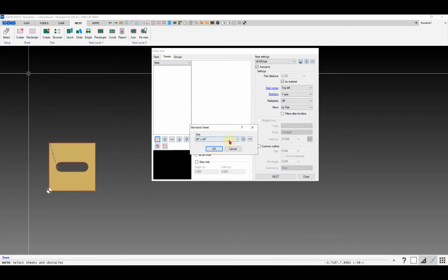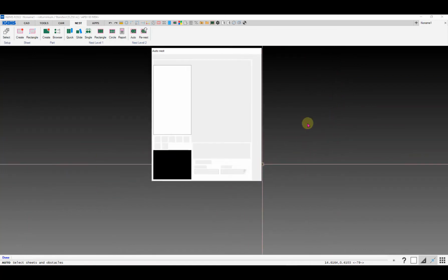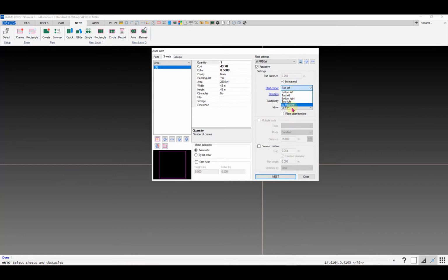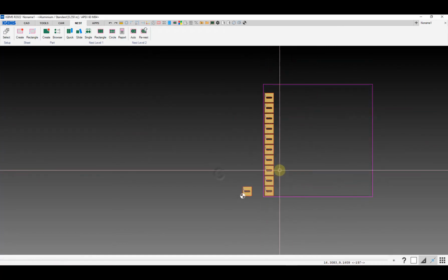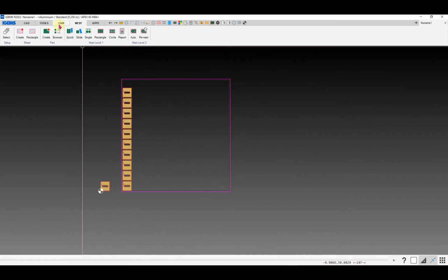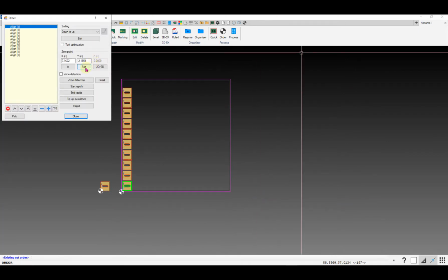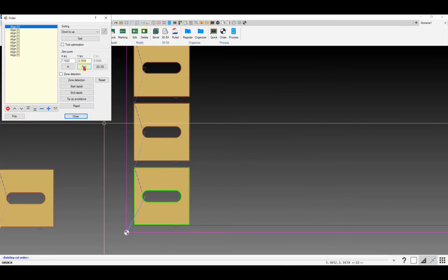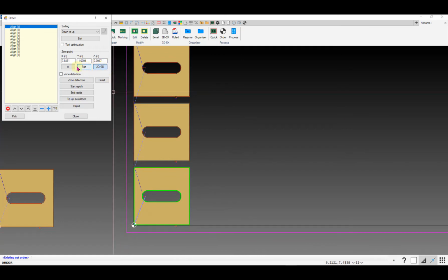And we'll just give it a sheet size here. Actually, change my start corner. Stop and OK. So they'll all be in the same orientation as the original part. And key thing when you nest 3D 5-axis parts, when you do the order button for the sheet, rather than clicking the part button, because if I click on the part button, it's going to move my 000 point to the corner of that part. Ultimately, we want it on the corner of the sheet.